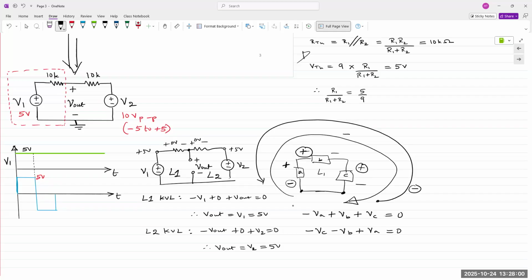Electrical voltage is defined as the potential difference between 2 points. So the key word is difference. If there is no difference between 2 points, then there is no voltage. If electrical potential at both points is exactly the same level, then it's 0 volts. No difference. So that's the simple analysis of how we can do.